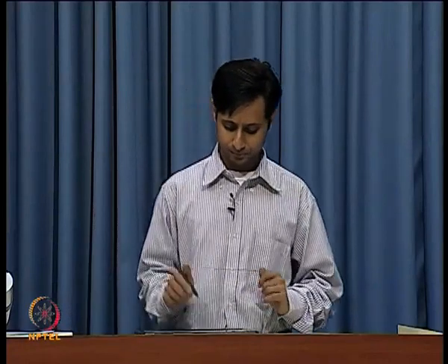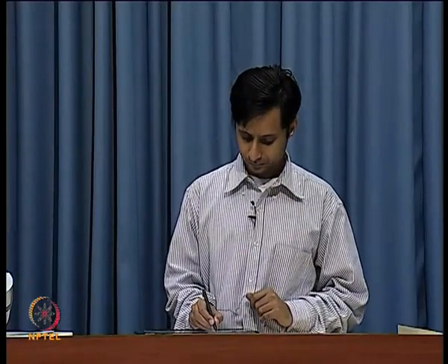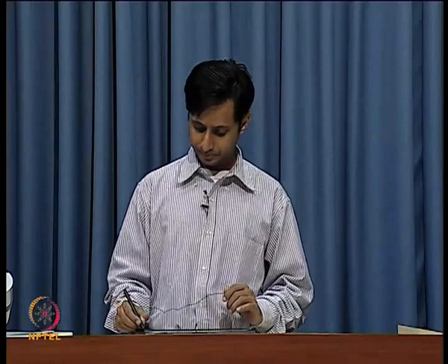So, strong inversion and saturation is good enough for this particular course. That is what we are going to stick to. Right, so this gives me a model of the noise current in shunt with the channel.